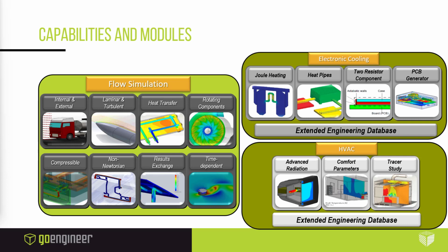Oh, and with using the time-dependent capability here, you're able to calculate the response of heat energy in fluid mediums as a function of time. For example, we can see temperatures and how they develop as a function of time, and when different components see the highest temperatures during a heat loading cycle, for example. Also, with the rotating components capability here, we can simulate and analyze pumps or impeller designs by assessing the rotation of our fluid mediums in and around designated rotating geometries.